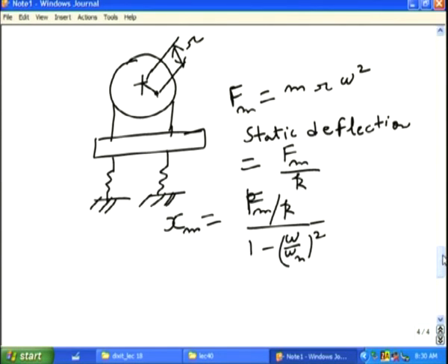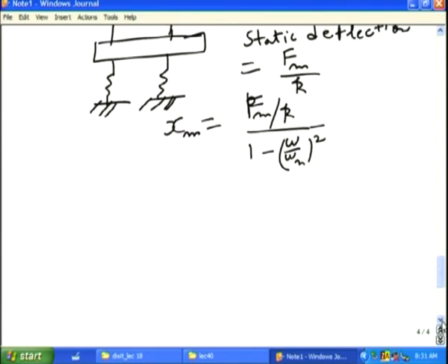When the force becomes less, then the deflection is more. This type of phenomenon occurs in dynamics, which is not found in statics. That force is more but the deflection is less, force is less, deflection is more. So we say that this is the out of phase vibration. Now a similar type of problem can be studied here, that is called whirling of shaft.